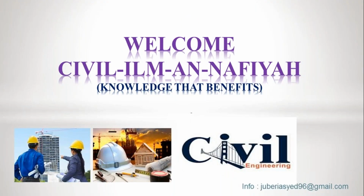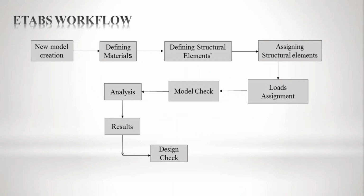In this video, I'm going to explain how to create the section properties. Here the sections are nothing but beam, column and slab sections. If we look at this ETABS workflow, we have already completed the first step and the second step. Now let us see the third one, which is defining the structural elements.